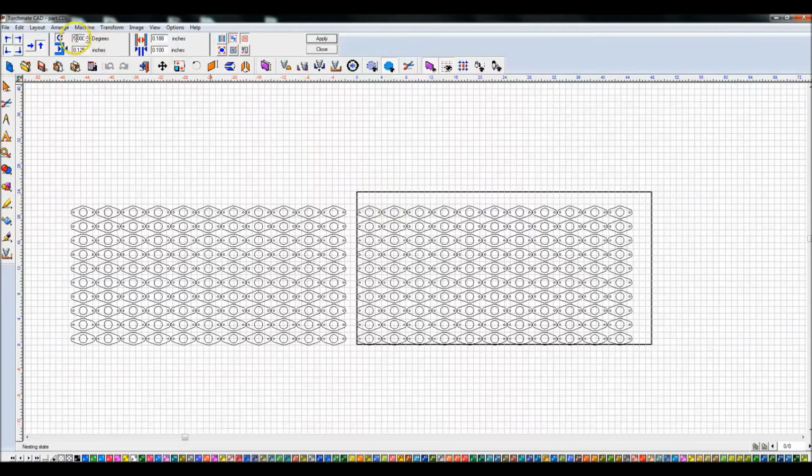The smaller you make this number, the more your computer is going to work to test each part and rotate it. If I set this at 90 degrees, it's going to rotate a part maybe a couple of times. If I set it at 5 degrees, you can imagine what is 360 divided by 5. It's going to be rotating each piece, I don't know, 15, 16 times or so, and it takes much longer.